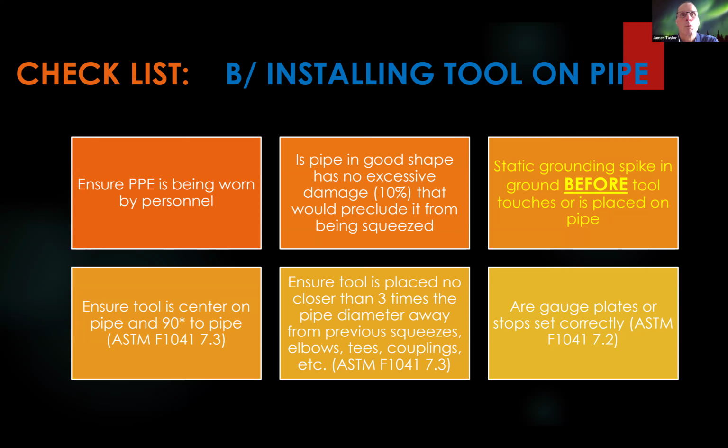A good idea when you have that spike grounded, stuck in the ground, pour your half bottle of water, kick it around the truck or van, pour it around that spike so it just seats that brass spike, copper spike, whatever you're using. It gives it that much better of a connection to ground. And dry, airy dirt with air between it, this gives a nice solid connection to ground.